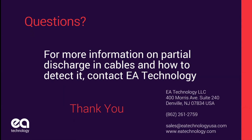On cables longer than the length limitations, can you confirm the RFCTs are still effective to see into the cable up to the limitation? As with everything in the PD world, there are no hard and fast numbers, but you can see PD that might occur. Yes, because the cable's longer doesn't mean you won't see it. It just means if it's past the point where you'd see it, you're not going to see it. But if it's within that first few kilometers, yes, you will definitely see it.